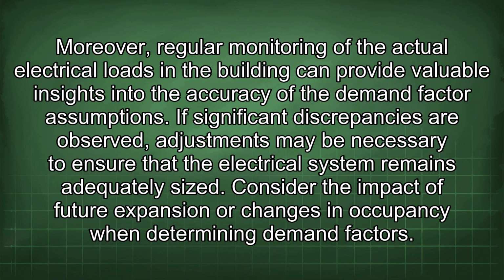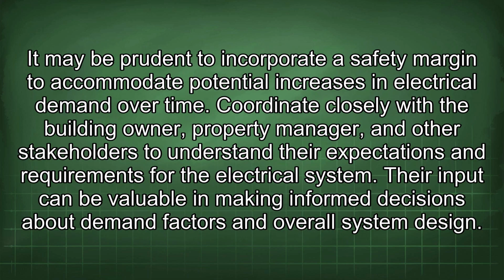Consider the impact of future expansion or changes in occupancy when determining demand factors. It may be prudent to incorporate a safety margin to accommodate potential increases in electrical demand over time. Coordinate closely with the building owner, property manager, and other stakeholders to understand their expectations and requirements for the electrical system. Their input can be valuable in making informed decisions about demand factors and overall system design.